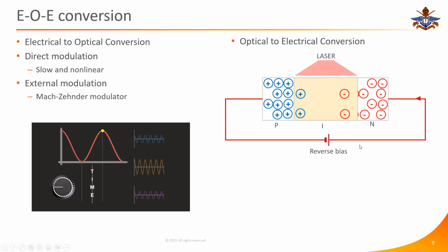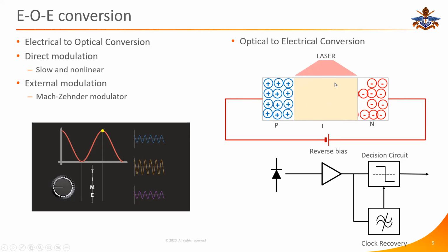In order to detect light, we create specialist PN junction diodes, where we have a big region with an intrinsic region, where there are lots of bonds between electrons and holes. And if I create a bigger area, it's easier for it to capture more light.